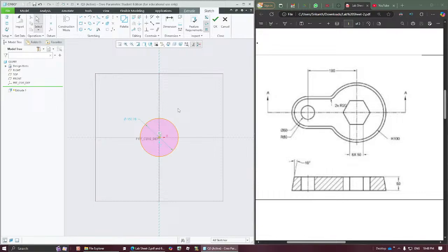We'll get to learn a bit about this anyway. So the first one, this arc has been created and its radius is 50. I'll have to trim this by moving these 2 points with the mouse button. The radius of this is 50, so change it to 50.